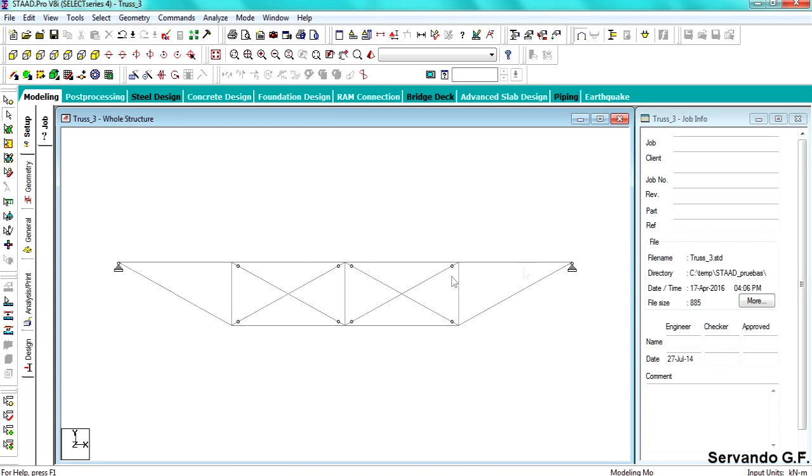And the same for designing these beams, because probably you're gonna design those beams to have the same cross section, these beams to have the same cross section, and those ones to have the same cross section, based on the worst case scenario that you're analyzing.